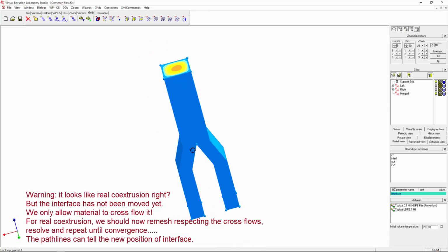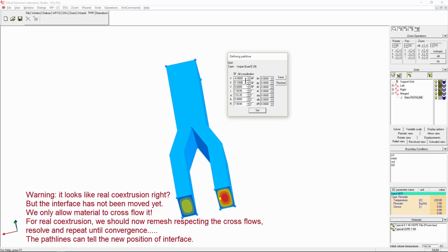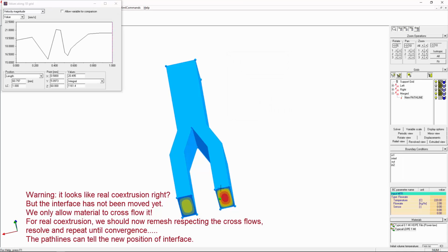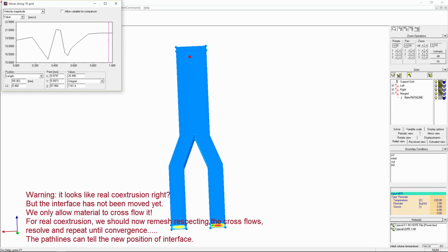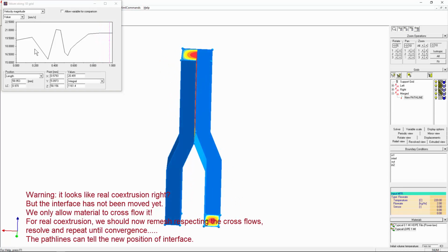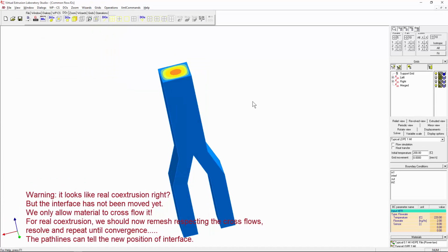At the same time, of course, I can do tracing of particles. We can define a path line, let's say here. We click set. We can see that this seed is coming through the boundary and goes to the second grid. We see the final point ends up on the left domain, so it really went across.